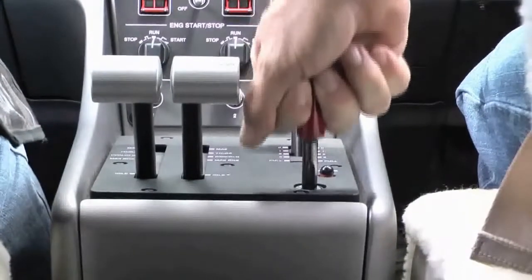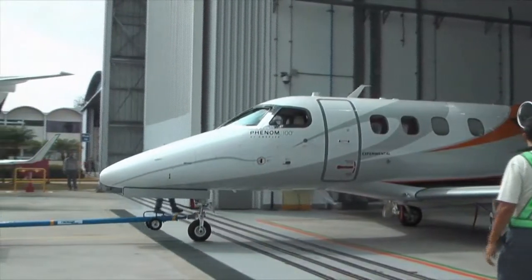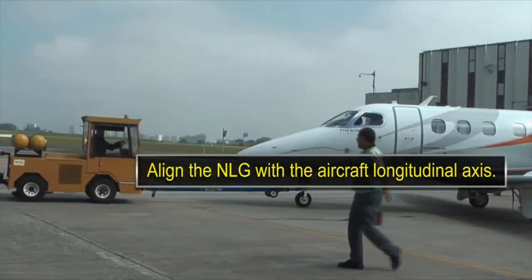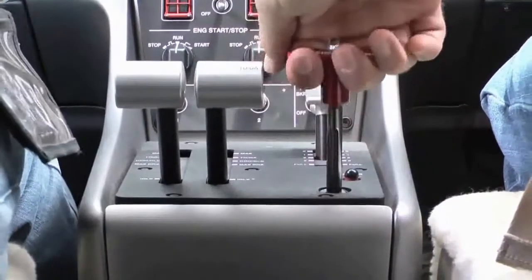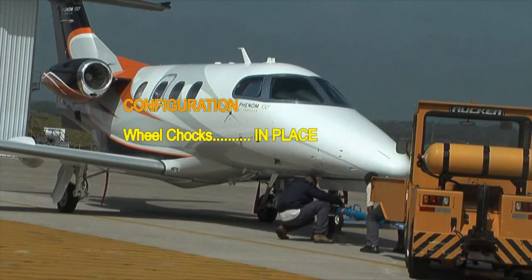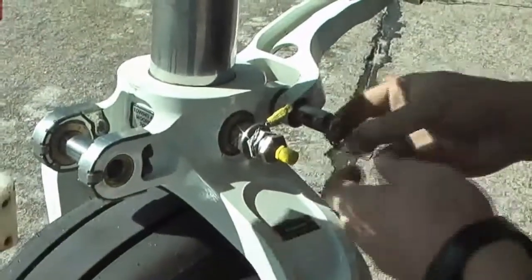Remove the wheel chocks from all tires. Release the emergency parking brake handle. Tow the airplane slowly straight ahead before turning. Complete the airplane towing in a straight line for a minimum of 3 meters. Set the emergency parking brake and remove the tow bar. Connect the nose landing gear torque link.